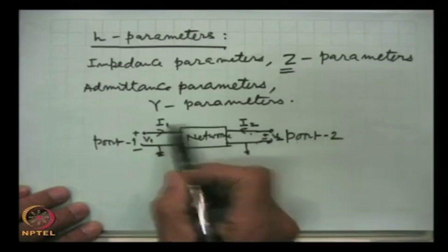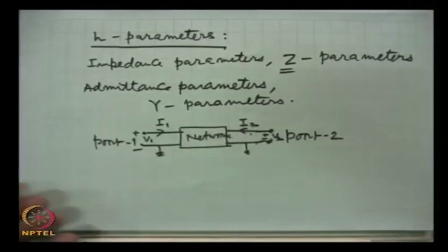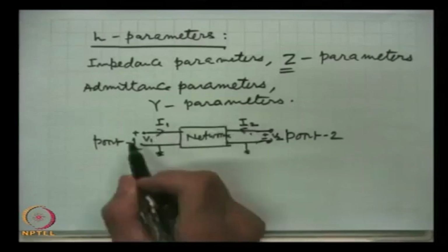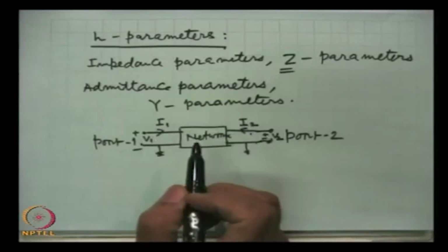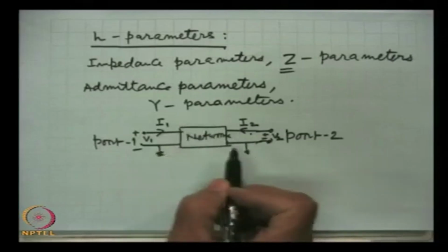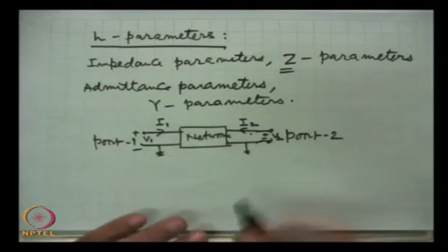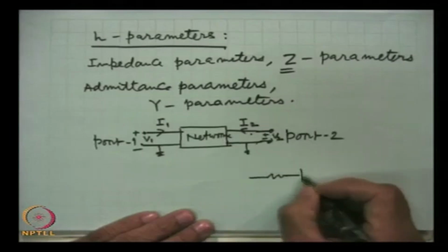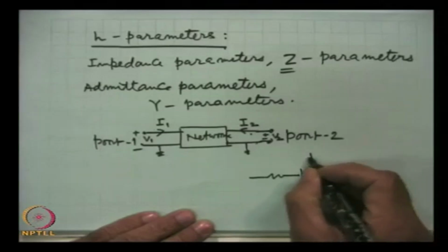Now, these currents and voltages are total currents and voltages, because as I have said earlier, in an amplifier the AC signals are superimposed over the DC. So, these are the instantaneous total values, total currents and total voltages. Now, our transistor fits in, that is also a 2-port device like this. Here is the transistor circuit. This is a simplified circuit. Actual circuits we will be drawing.